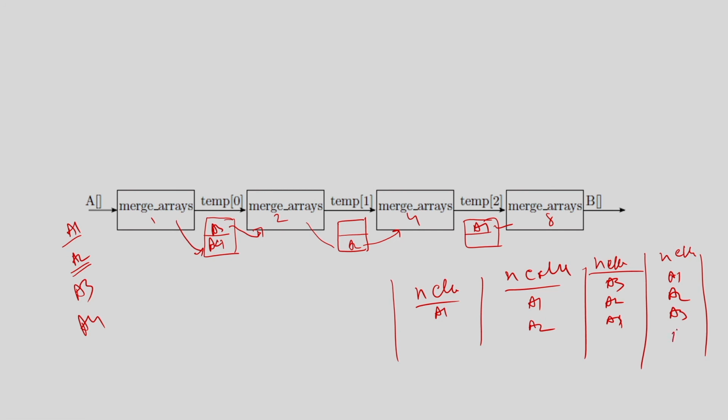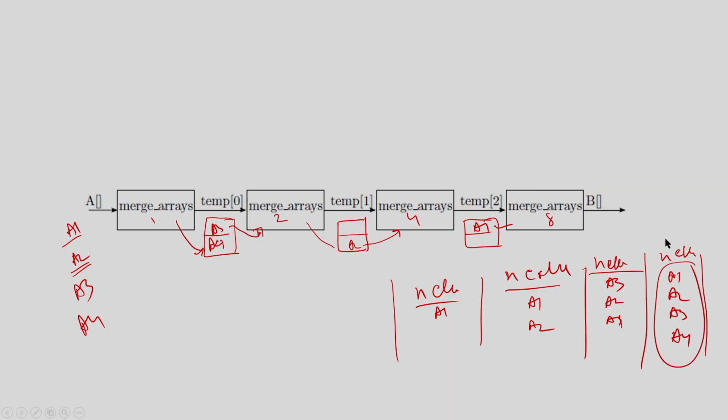So, now at this point you can understand that all these 4 modules are actually running in parallel, and they are running on different sets of data, right. So, this is the maximum benefit, and this will continue for the next n clocks: it will take A5, this will take A4, this will take A3 and this will take A2, right. So, this way things will continue. So, what is happening here? I am not able to improve the performance for one set of data, right. That is already achieved, but now I am doing task level parallelism, right. So, different arrays will be processed by different blocks in parallel, and I can actually get the maximum benefit, okay.